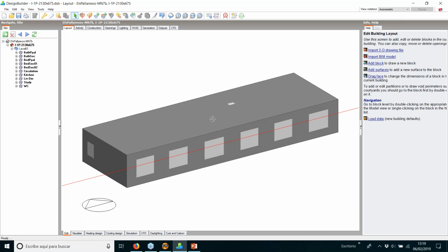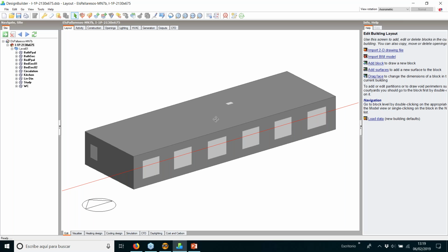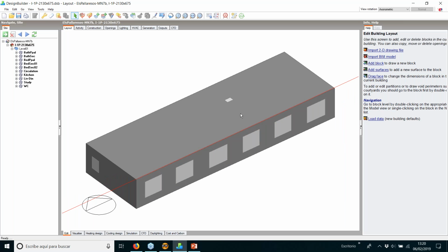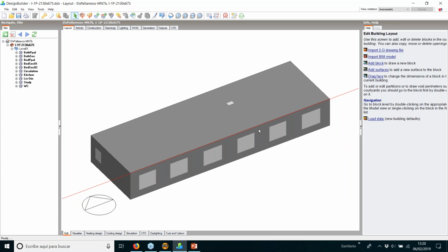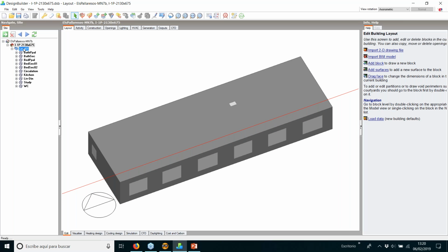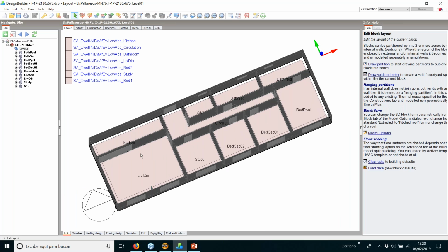When you are going to run an optimization analysis, the first thing you have to do is prepare your model, I mean, the geometric part of the model that you can see here. For example, in this case, you can see that we are modeling every space in the house as a thermal zone.